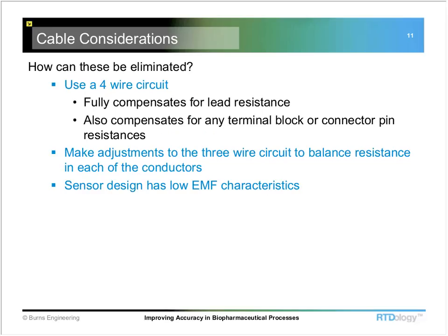Right. That's the best way. I mean, they typically would have the right equipment to be able to do that. You may see things like the cable may be labeled with "do not cut cable or accuracy will be affected." And typically what's happening there is that they've put some kind of a trim resistor in that cable, typically at the end of the cable where you can get at it to make the adjustment.